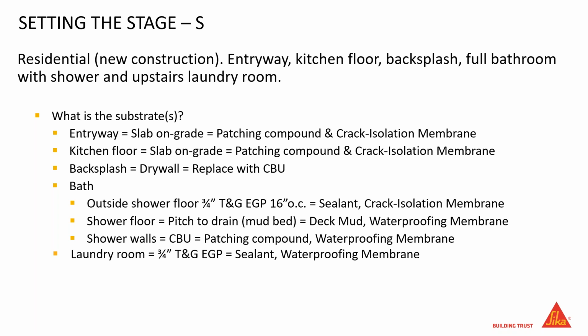Laundry room. Again, it's a 3/4 inch tongue and groove, exterior grade plywood. Again, the sealant to fill in those 1/8 inch tongue and groove gaps, and then a waterproofing membrane to go over the top of that.